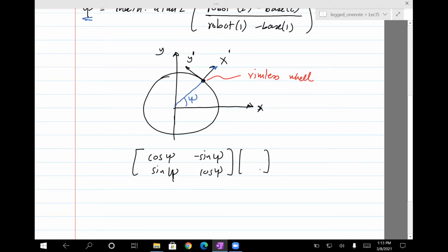Remember that when we talked about the horizontal and vertical components, we talked about g cosine gamma, which is the z component, which does not change. It's actually going to be negative. And the component along the horizontal is going to be g sine gamma. Now this g sine gamma is going to be in this direction, because it always is towards the heading.